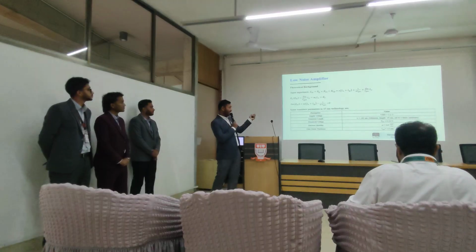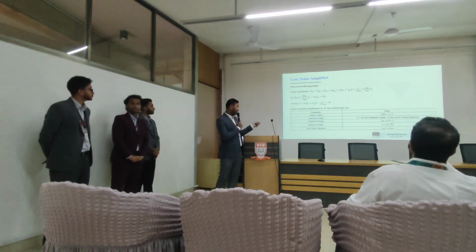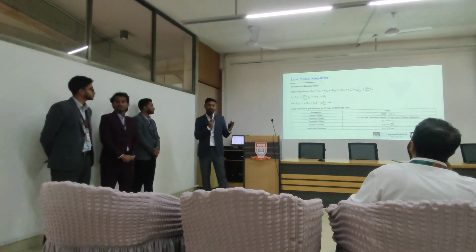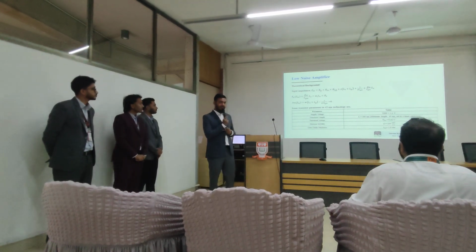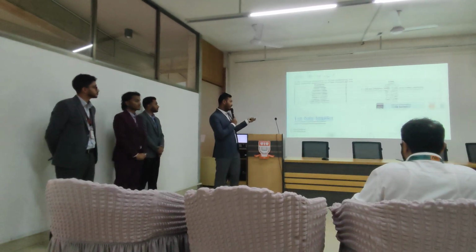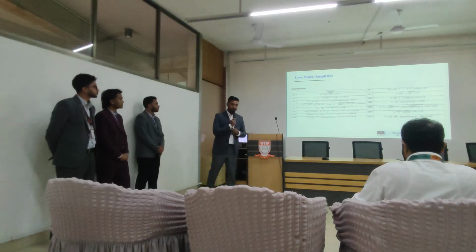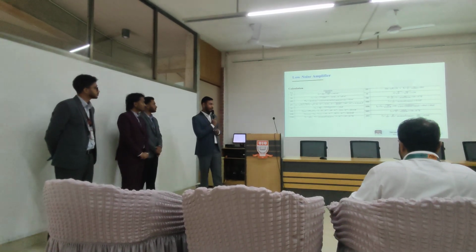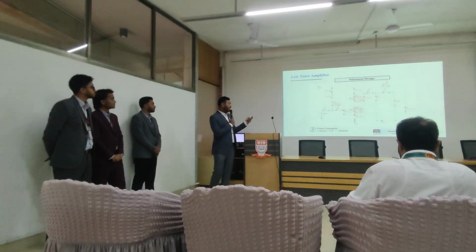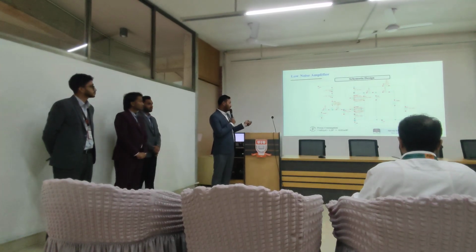Then coming to the next slide, here is the theoretical equation for the low noise amplifier. Based on the 45 nanometer CMOS technology process, we calculated different values shown in this slide for inductance, capacitance, and the transistor dimensions to optimize the performance. This is the complete circuit diagram for the low noise amplifier.